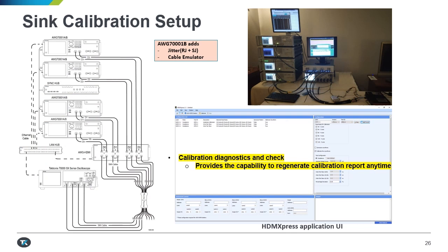The Tektronix sync setup has link training and debugging capability, to test link training in advance before starting the test procedure. When it fails, a detailed log file is provided to identify the issue. Use the HDMI Express utility tool for closed loop calibration for all 5 measurements. Here is the schematic diagram of the sync setup for AWG stack connections. Actual setup picture taken at the MOI event.